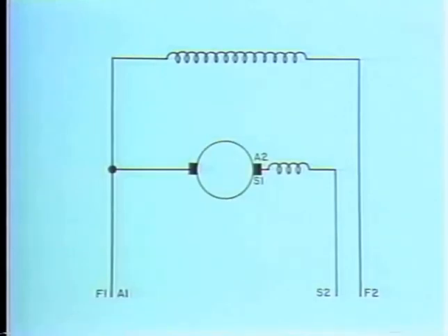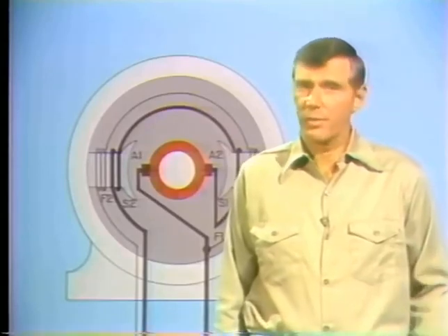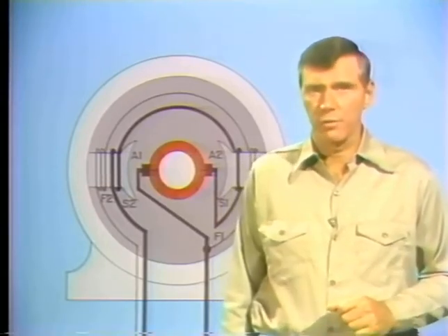Notice the field and armature markings. They tell the story. Now, when you're working on a compound motor, the thing to keep in mind is organization. You've got to make sure each lead is marked so you won't make any mistakes when you're reconnecting the motor. And you've got to double-check each connection you make to be sure it's right. Oh, one other thing. Bear in mind that if you open the shunt field, then what you've got on your hands is a series motor and all the dangers that go along with it.